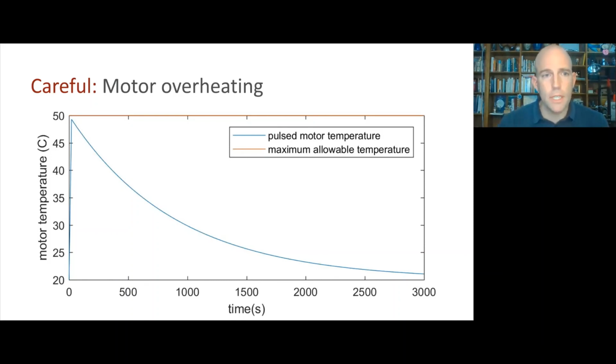It's a little deceptive. And then if we turn off, disconnecting the leads using the alligator clips very quickly, then the motor will take a long time to cool off. This is a little shy of an hour. If we instead waited, say, 10 minutes and then plugged it back in, stalled it for 20 seconds again, we're going to exceed the maximum sustainable temperature and burn up a motor. So keep an eye on this for Project 4.